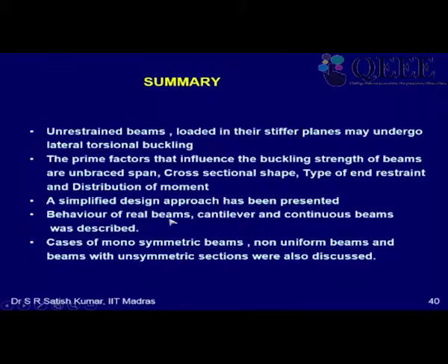For the behavior of real beams, cantilevers and continuous beams, we have not gone into it, we will leave it, but basically for real beams we use an empirical equation for lateral torsional buckling. For cases of monosymmetric beams, we can use a simplified equation, and unsymmetric sections also we have understood what will happen. Okay, so if you have any questions with reference to the theory, you can ask.